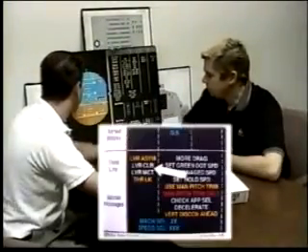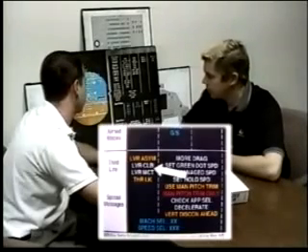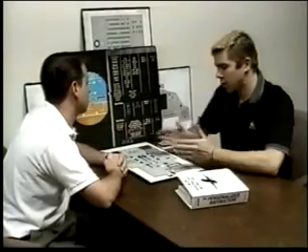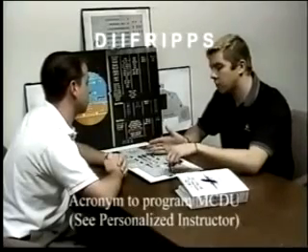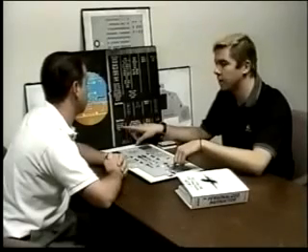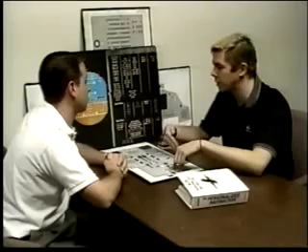Lever climb, lever MCT. Describe those for me. Basically, it's just the computer saying, hey, you need to move the thrust levers to the specific detent. In most cases, we're seeing lever climb. When would you get lever climb, say on takeoff? Lever climb is going to occur during the thrust reduction altitude we set on the performance takeoff page. At the thrust reduction altitude, lever climb is going to flash, reminding me to move the thrust levers from either TOGA or flex into the climb detent.